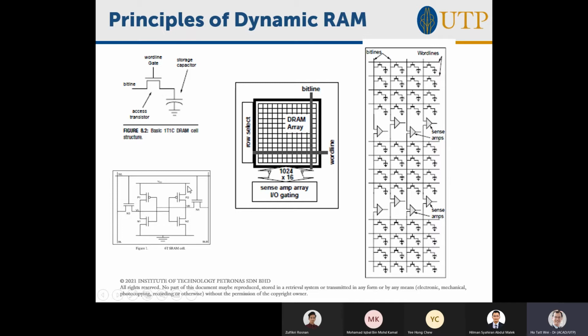Is it worth it? I would argue yes, the industry found it worth it. Why? Because you can compare the difference. If you're only using 6T, you can get maybe a 1 megabyte cache. But if you use 1T, you may end up getting a 6 megabyte cache. So you've got between 5 to 6 times the capacity, which is a lot. It's not a small amount. So that's why people are willing to go through all this trouble.